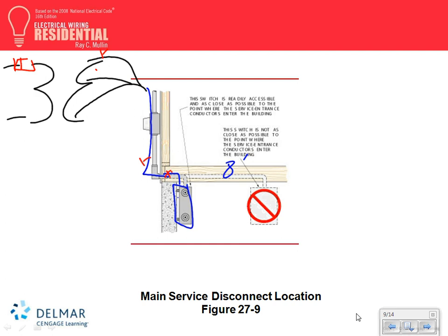But the minute that you come over here, what do you put? The first thing, you put your 100 amp circuit breaker. Now any conductor coming out of this panel is protected with a 20 amp or 30 amp or whatever. But these conductors from here all the way up to here, the only protection that they have is the fuse on the primary of the transformer, which most of the time is going to be oversized. That makes sense? Red, no? Everything you said makes sense, but I don't understand.